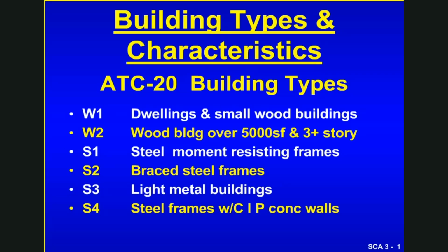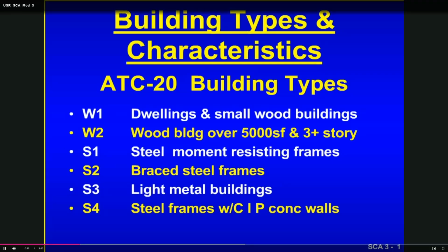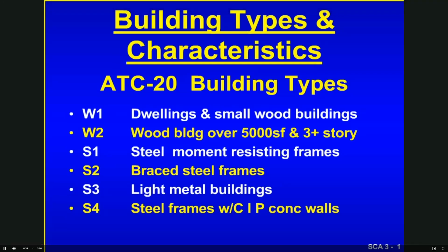And that letter is followed by a number which indicates the lateral load resisting system, whether it's a moment frame, box building, or diagonally braced building. So S1 would stand for a steel frame, and C2 would stand for a concrete shear wall box building, and so forth. In addition to these types of buildings, there are 4 specialty types.